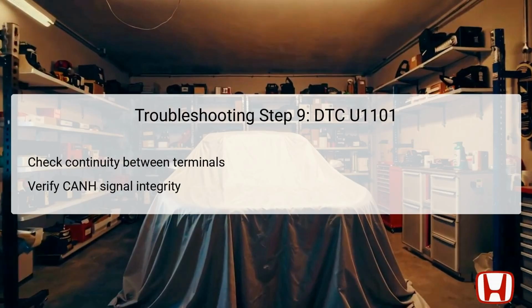If continuity is confirmed, it suggests that there are no breaks or faults in the wiring as far as these particular connections are concerned, allowing the technician to continue troubleshooting further. Conversely, if no continuity is detected, it indicates an open circuit, which will require the technician to trace the wire between the PCM and the engine mount control unit for repairs or reconnections.